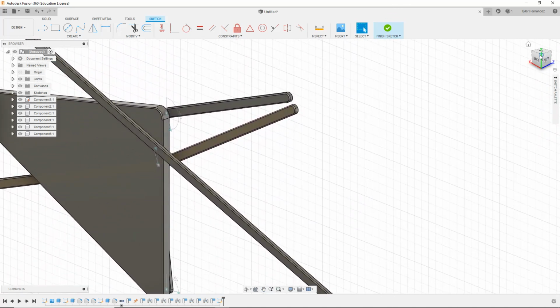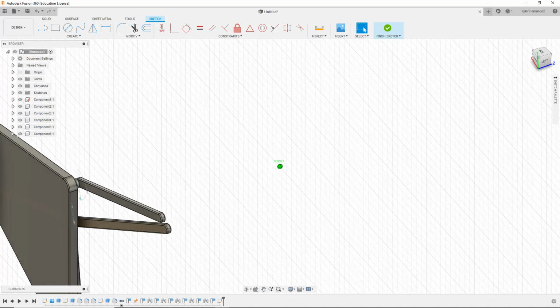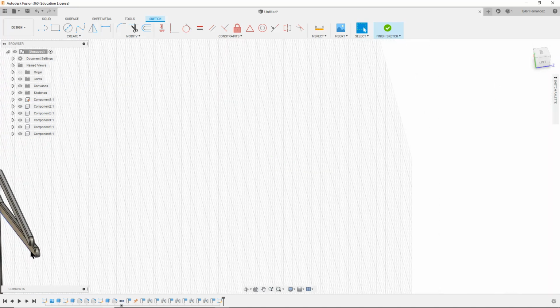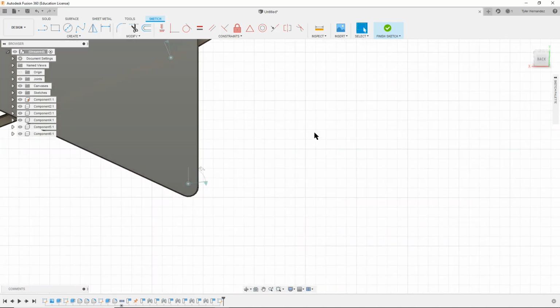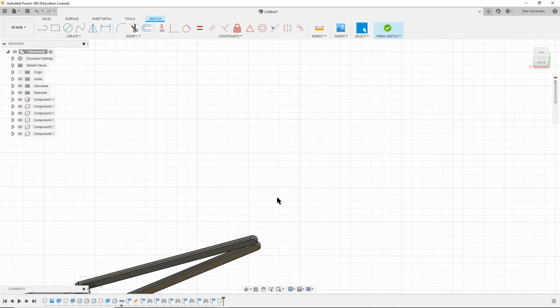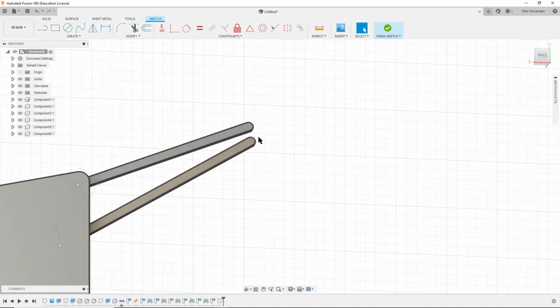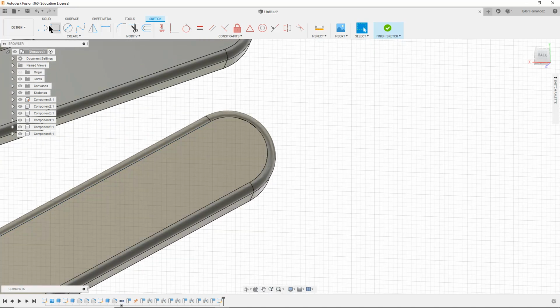What is going on here? And what I want to do is pull it back. So I want to put a circle on the end there and extrude it backwards. So I'm going to zoom in here, use my circle tool, find the middle of this circle, looking for this circle icon there, drag it. I'm going to make 1 millimeter and hit enter and finish sketch.